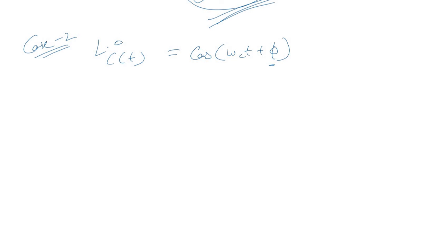Okay, so now if we perform the same analysis, the first step is the multiplier. So we multiply the AM signal with the carrier signal, that is AC cos(omega ct plus phi).